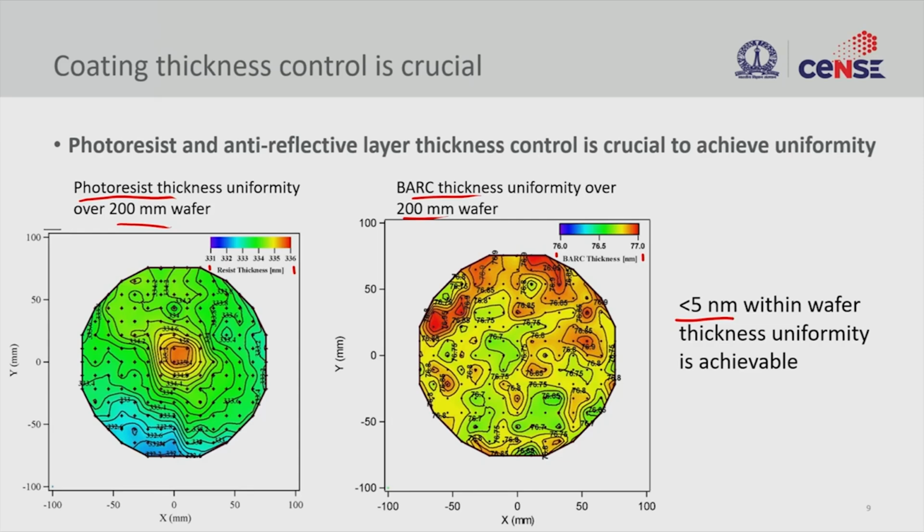Okay. So with this we come to an end of this reflection problem. So how the reflection is affecting your critical dimension, and also not just the reflection from the surface and interfaces, but also the thickness variation. So if the resist thickness varies, how the anti-reflective coating layer could be used to mitigate this issue.